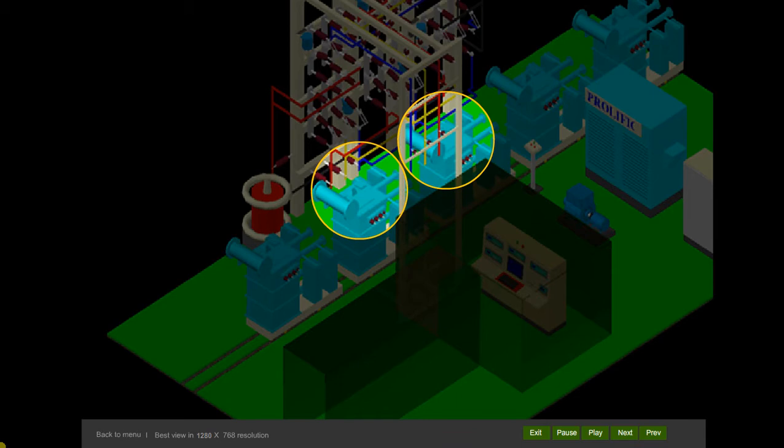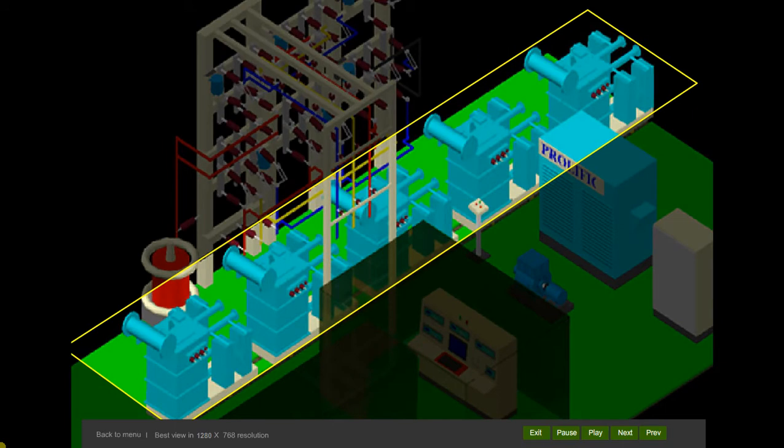By using one TAT lab, you can test about 50 transformers per shift of 8 hours, assuming connection and disconnection time of approximately 3 minutes.